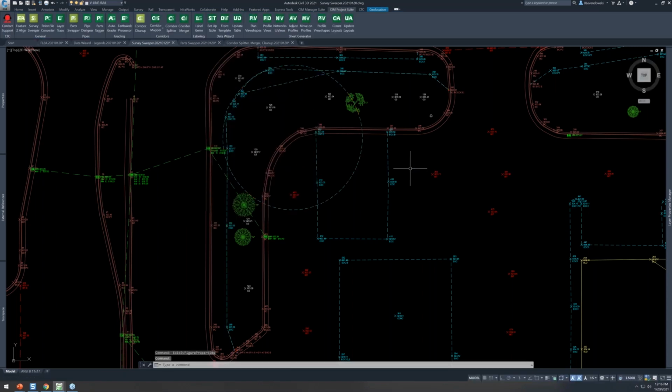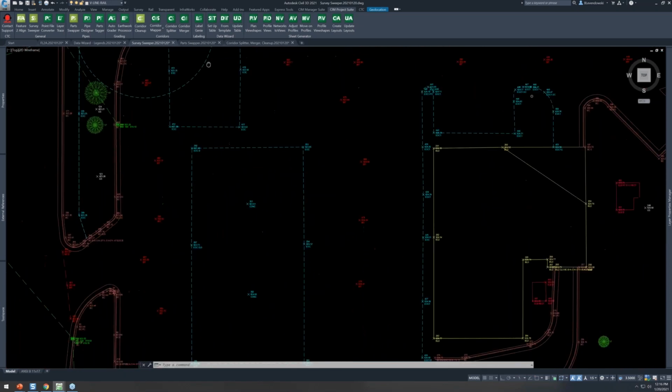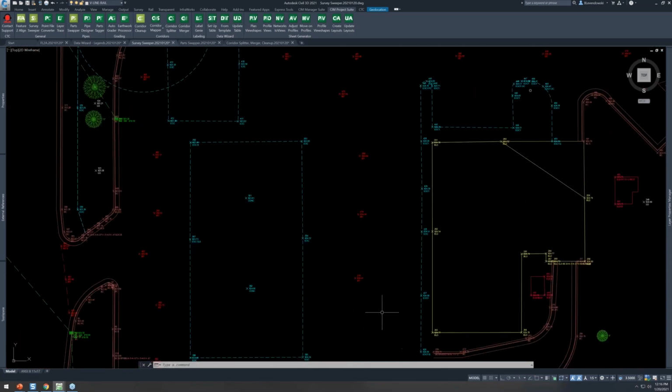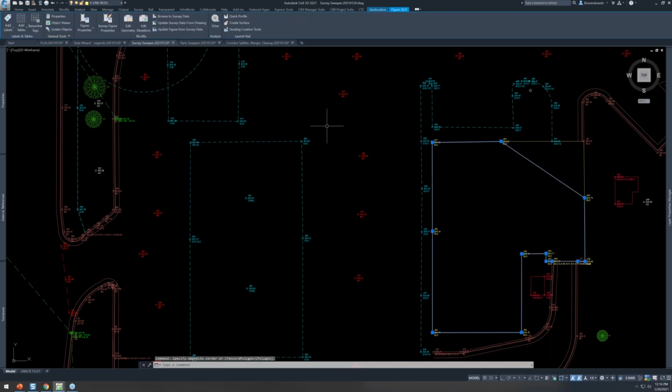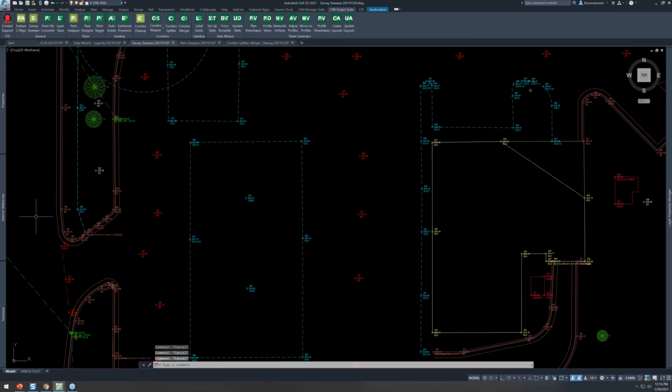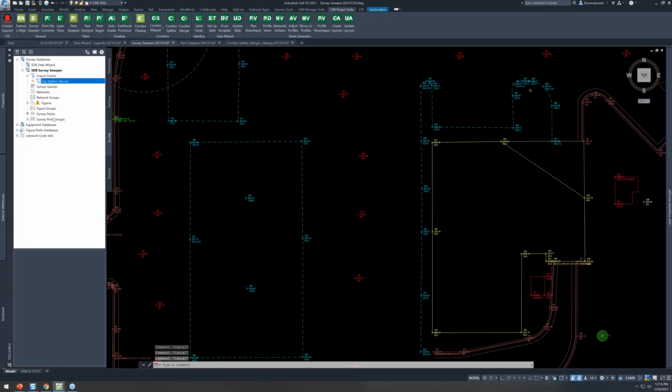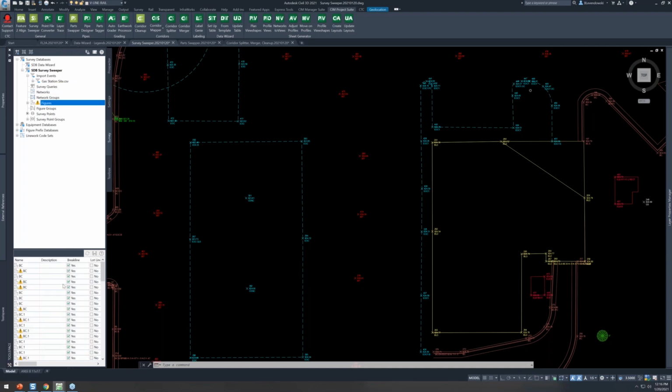Okay, if you did survey figure editing, which is another powerful tool when working with survey databases, if you then go and do point changes like this and refresh your line work, what it does is it always creates all these duplicates. And the challenge is that these things are in your database as well, okay? So my figures in this database, they are in here. And why is that important? It's because my break lines for my surface come from my survey database, okay?